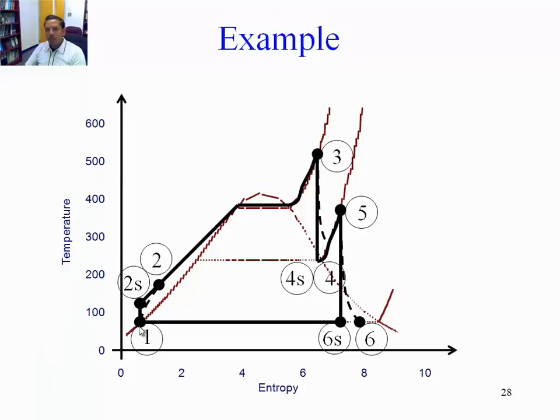Okay, so this is the concept of reheating the water vapor in the Rankine power cycle, and this is how we analyze a power cycle and how we found the cycle efficiency. And we demonstrated that for the same type of conditions, the overall cycle efficiency actually increases, which is what we expect out of these modifications.